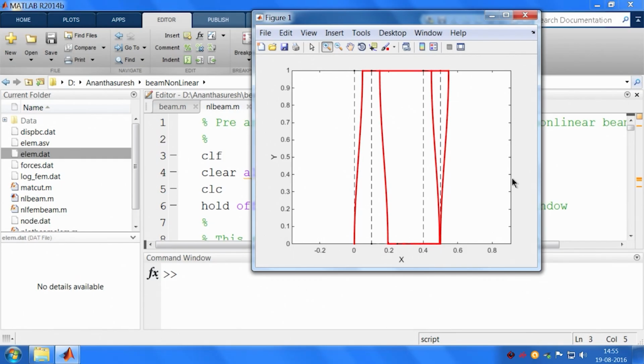The reason that lever is needed is for this spacing, the original spacing from here to here, there will be a little bit of downward deflection. From here to here for the second stage there will be a different amount of deflection. So, if you know those deflections ahead of time, you couple them using the corresponding lever ratios. There were letters A and B. If you arrange them correctly, you can make sure that even under large displacement, this particular stage will not have any vertical motion. Okay. So, now we have a stage where applying force, it moves like this, right.